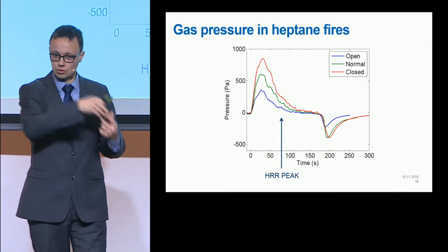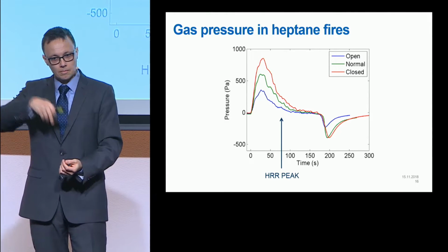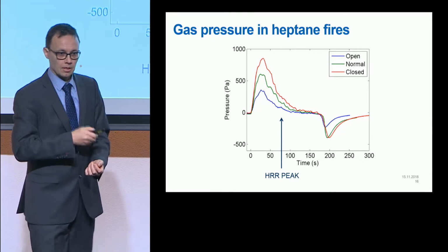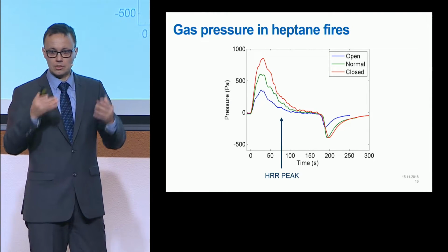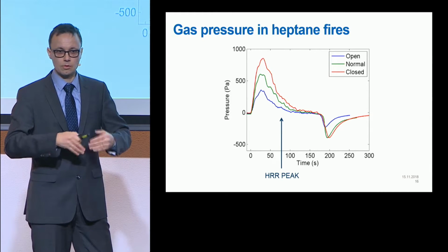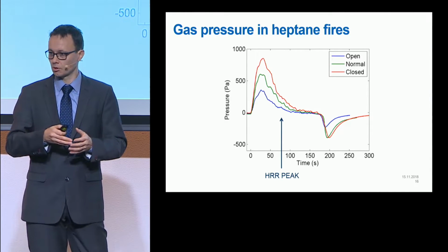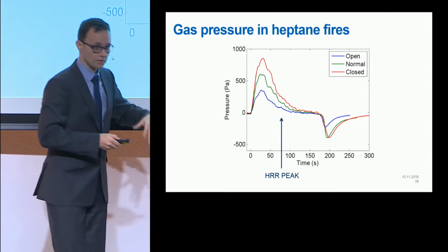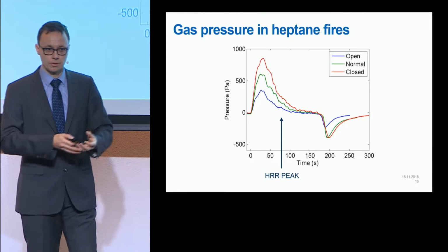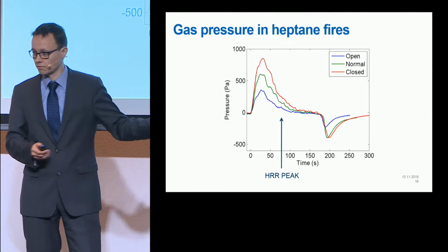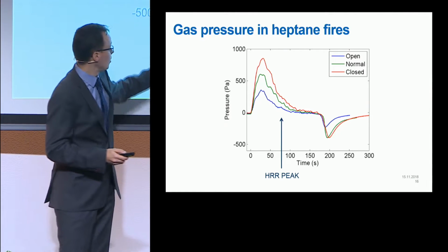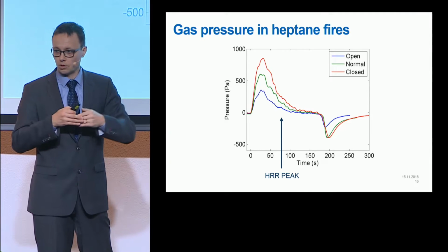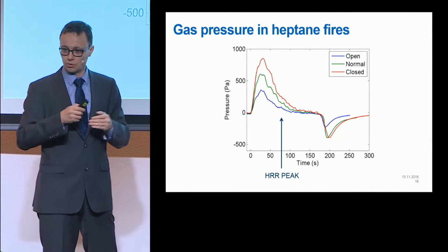So we not only have a source term, we actually have a drain of energy away from the gas phase to the boundaries. And also, when the average temperature increases, the relative increase of the absolute temperature is going to slow down. So the positive source term of gas pressure is going to decrease over time, while when the pressure increases, the leakage through the envelope and through the ventilation is going to increase.